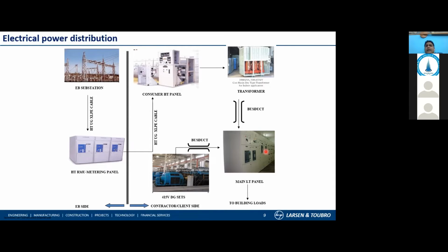Okay. You can take any of your buildings where DLF is constructing an office building, or Tata Projects is constructing a service apartment with G plus 10 floors, let's say, and every floor you are having 10 flats, 2-bedroom or 3-bedroom flats. So multiply by 10 floors, you have 100 flats. The electrical engineer first works out the load for one flat. He will assess how many light points and how many power points he is going to give.